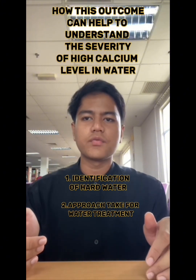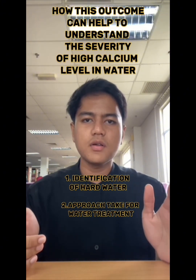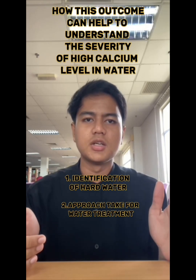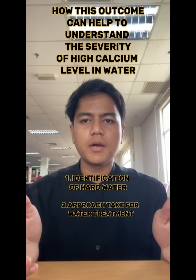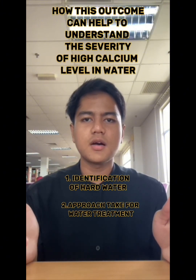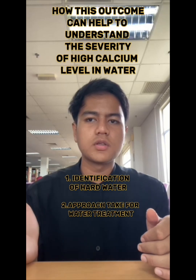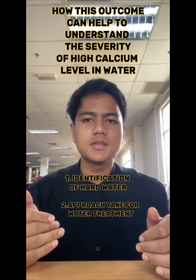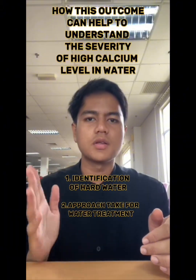A water softener or descaling agent reduces calcium level through ion exchange. It swaps calcium and magnesium ions that cause hardness with sodium ions. The water flows through a resin bed where the ions exchange, resulting in softer water.